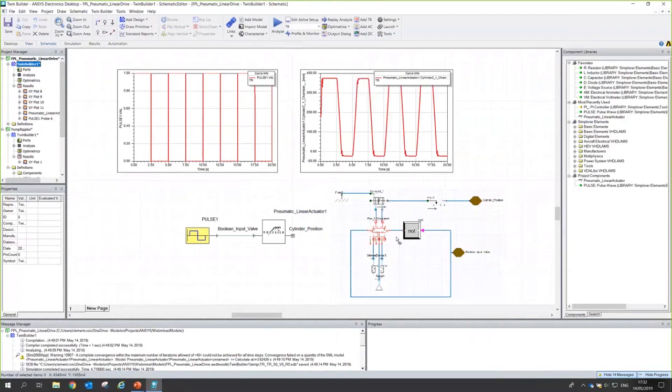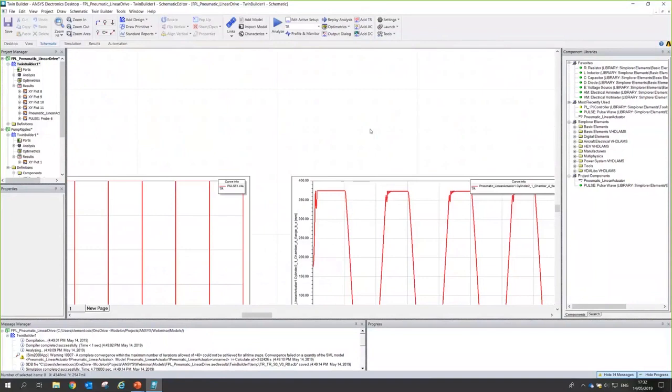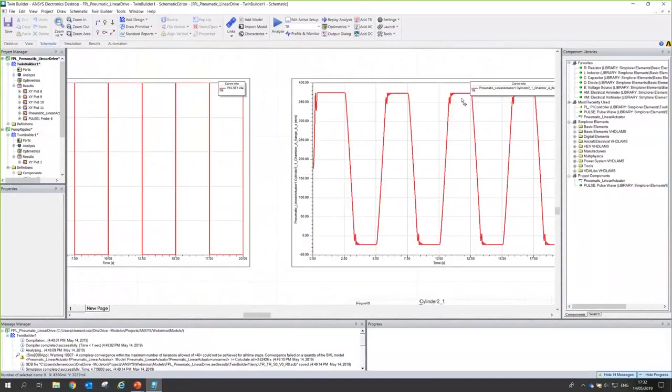So you have everything from the slide. I just took them separately, but that's actually the same information you have here. So the Modelica model with the open loop control, or the open loop input, the normalized command, and the answer of the cylinder with the dynamics due to, for example, compressibility of the gas.